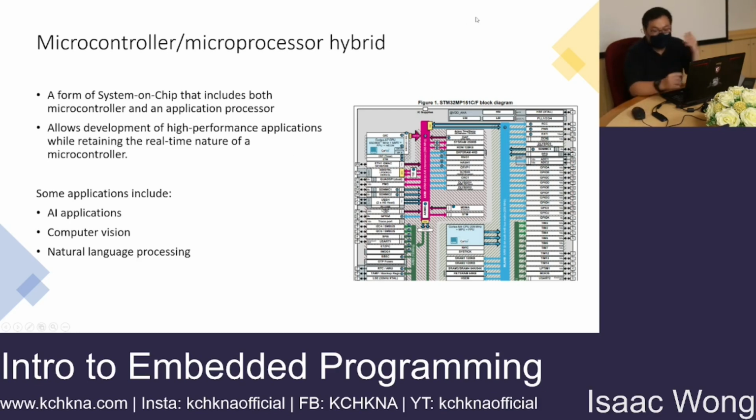So what does this actually do? Because they're on the same die, it's very convenient for the designer to implement in hardware. So this allows a designer to run high performance applications on the microprocessor here, while still retaining the real-time nature of a microcontroller by delegating some of the signaling and controls to the microcontroller here.